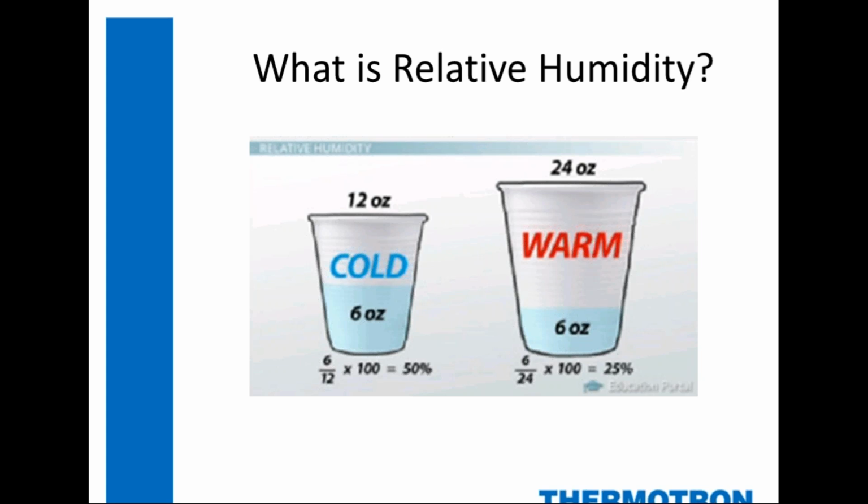And then just understand the difference between holding a precise humidity condition like 40 degrees C, 50%, which requires a humidity chamber with precise control. There are also test specifications which will simply say you need to run 50 degrees C at less than 20% humidity. So it's just calling for a hot, dry condition, but doesn't require you to hold to a precise humidity level. And we can do those without a humidity chamber just by injecting a dry gas.